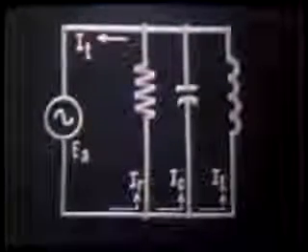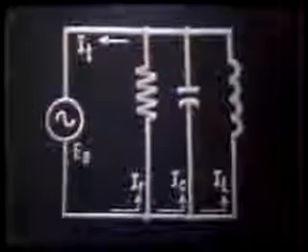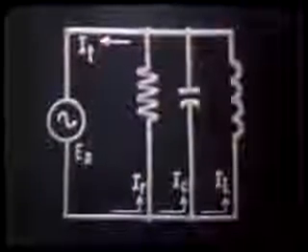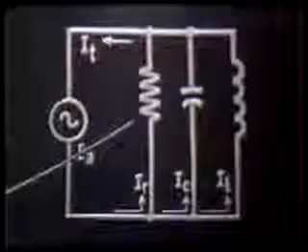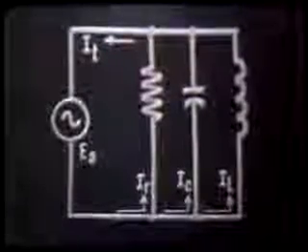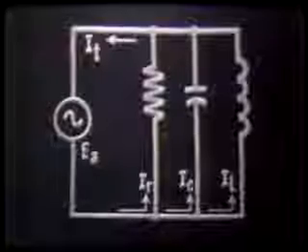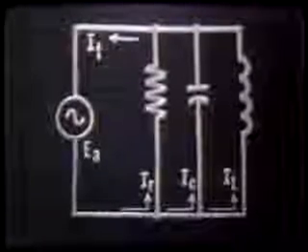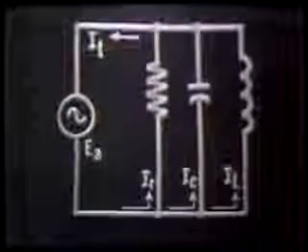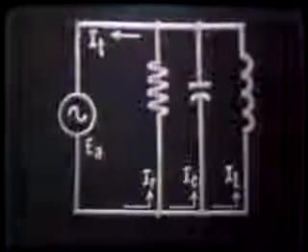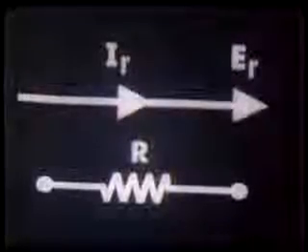Let's answer this question by reviewing the current and voltage phase relationship across each component. We'll begin by investigating the resistive phase relationship. The voltage across and the current through any pure resistive component is always in phase and is vectorially represented this way: IR in phase with ER. Note, ER represented here would be the same as the applied voltage since we do have a parallel circuit.